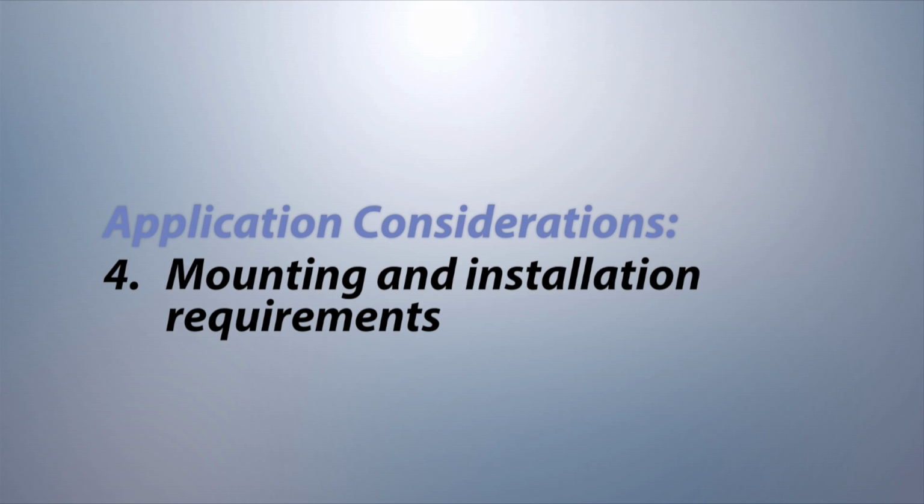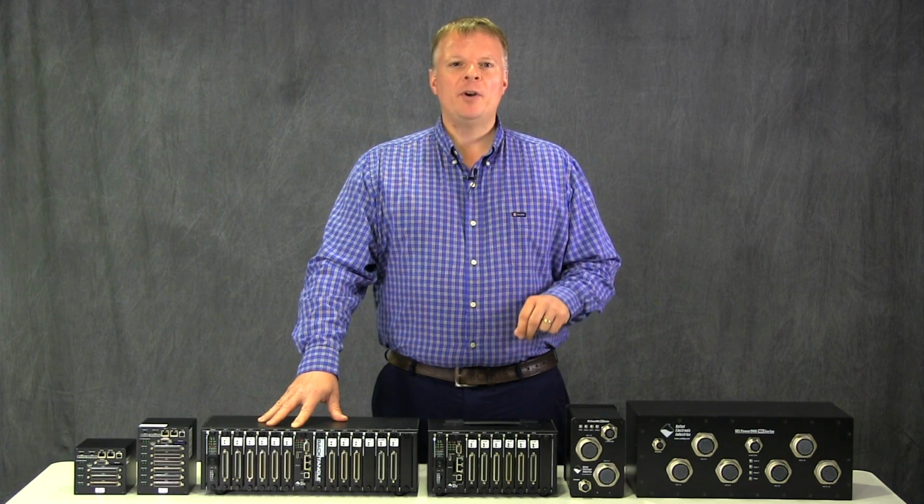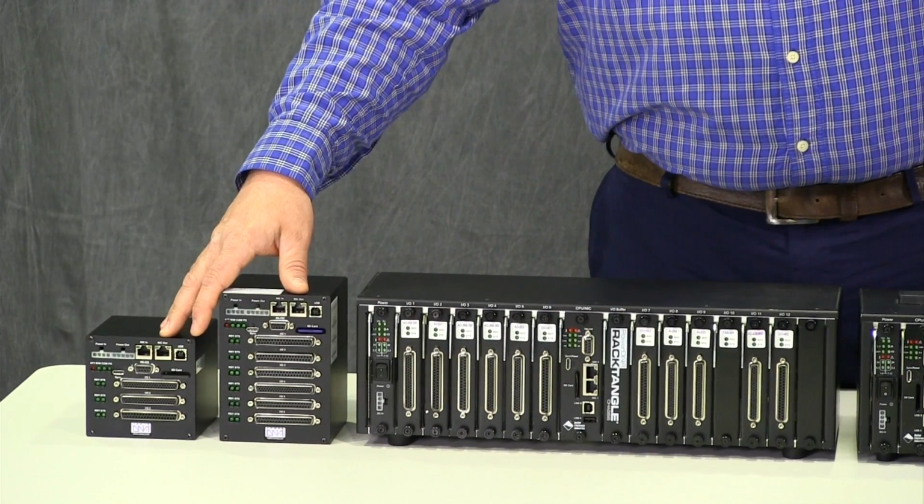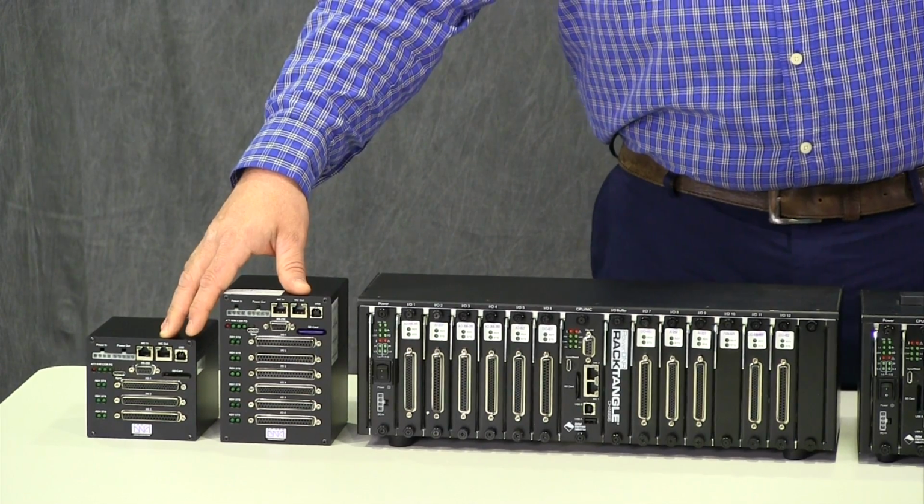Another consideration is how will you be mounting or installing your system. All of the UEI form factors have their respective mounting options, and they are all rather straightforward. But the deciding factor may be whether or not you are using a standard 19-inch rack. While the rack systems offer several 19-inch mounting options, the smaller cube chassis can be either mounted directly to a flat surface or a DIN rail using the respective accessories. UEI also supplies a DIN-ready rack adapter chassis for our cube.